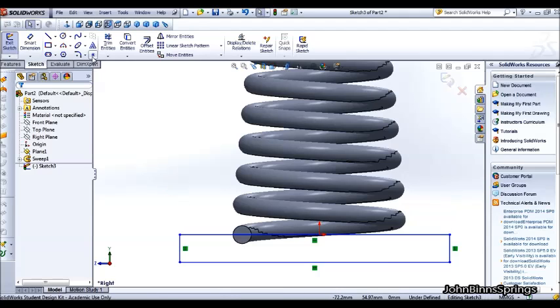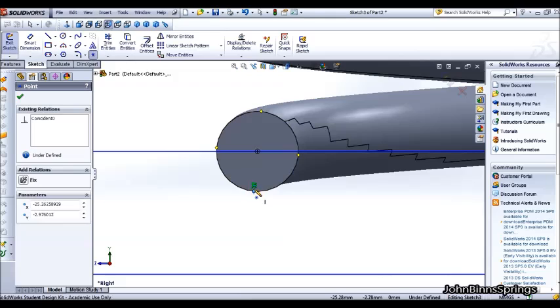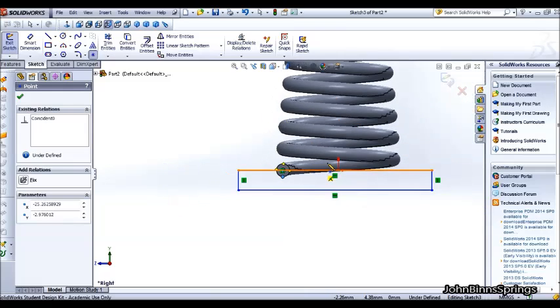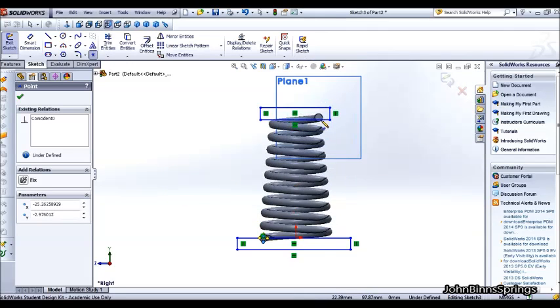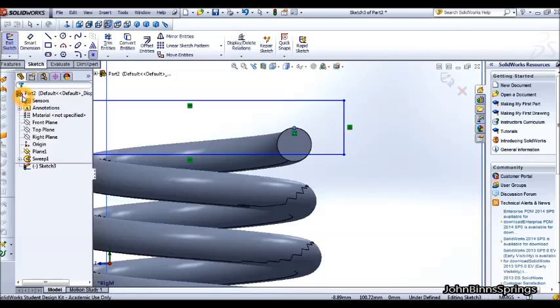So the best way to do this is to select the point tool again, zoom in, and hovering over the circle's face, and then just clicking when you can get to one of these markers that appear, and do the same for the top. And then tick that, and then you want to give it a dimension.